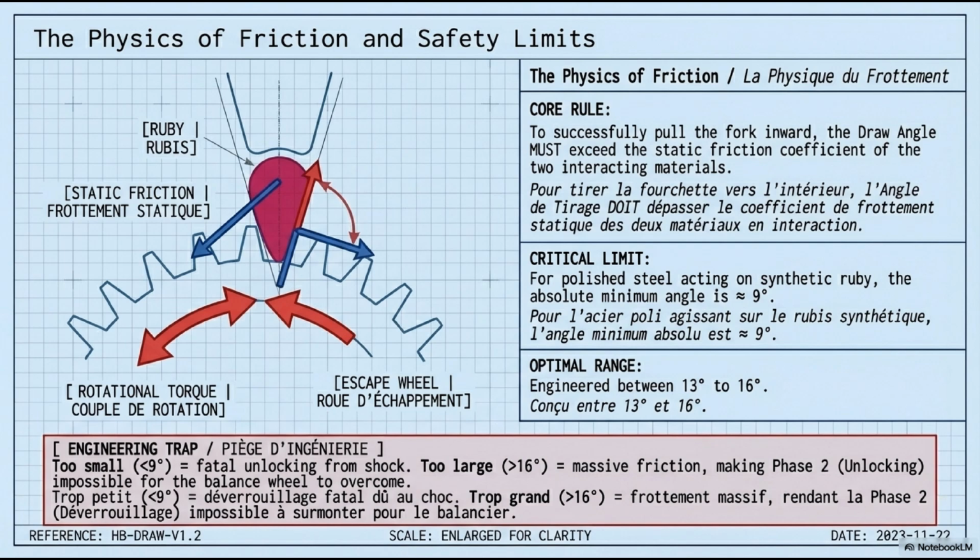The tooth locks on the locking face. Watch stops. Rest face stoppage, arrêt sur le plan de repos. The draw angle has a floor set by shock protection and a ceiling set by unlocking friction. The 13 to 16 degree design range sits safely between both limits.